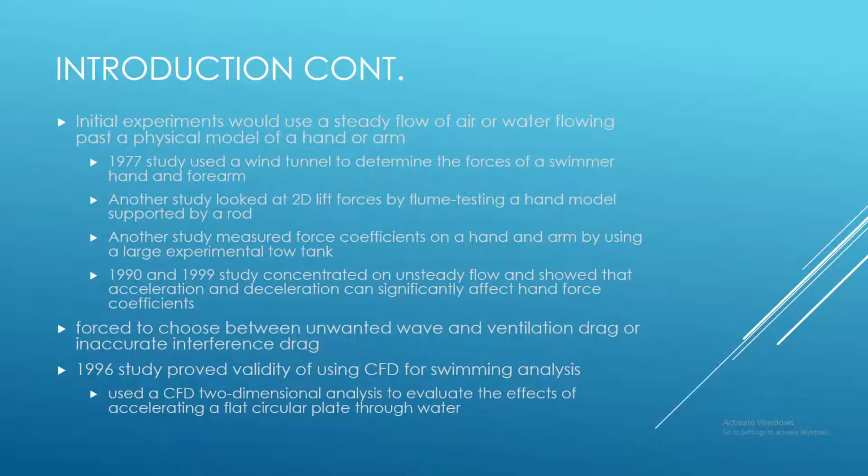Another study measured force coefficients on a hand and arm by using a large experimental tow tank. Although the lift calculations performed were three-dimensional, the arm model ended up piercing the surface of the water, resulting in extra wave and ventilation drag. A 1990 and 1999 study concentrated on the unsteady flow and showed that acceleration and deceleration can significantly affect hand force coefficients. Both experiments accounted for fixture drag, however, the effects of interference drag at the wrist were not considered.